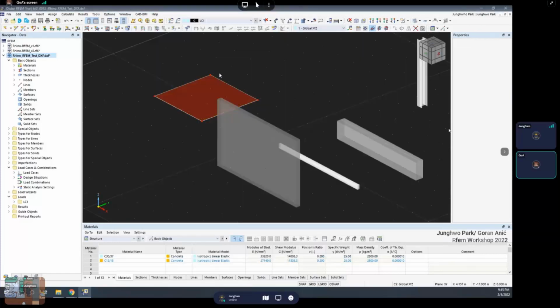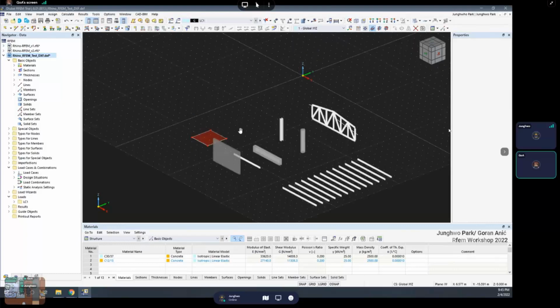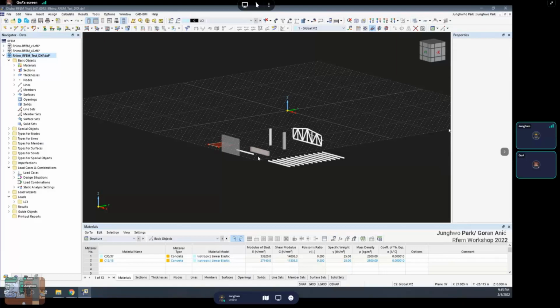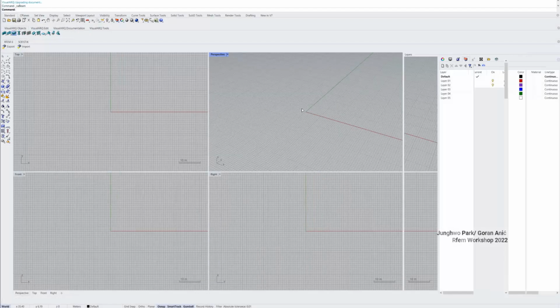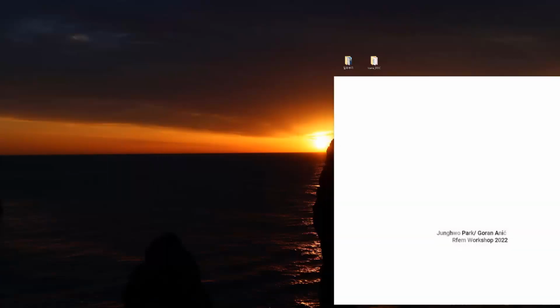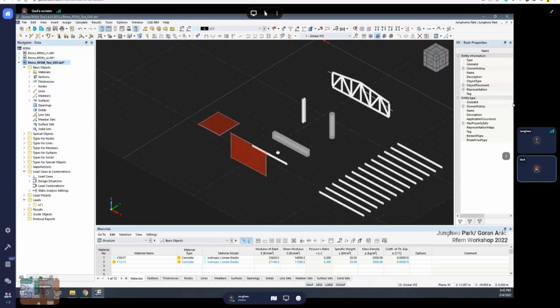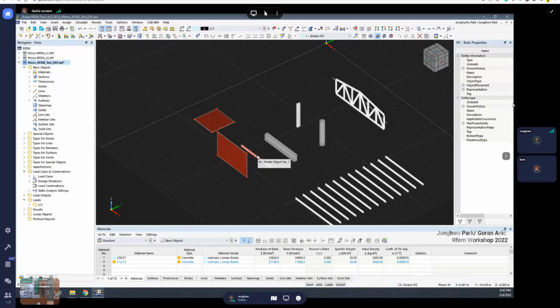That's what's nice, because now I'm thinking I can prepare my model in any 3D software. I can just make it clear with the bearing construction, and then when I import IFC, I can go from top to bottom and choose: convert this element to surface, or do not convert it for now. RFEM even has a great connection with, for example, Revit. Okay, that's interesting, very nice.